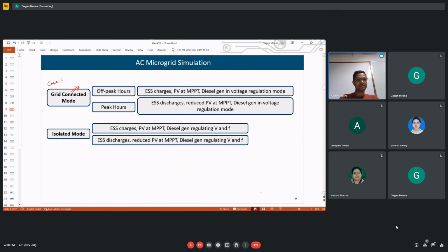So it is automatic, not manual. We don't have to give any instruction. As soon as the SOC goes below 30%, load will be curtailed automatically, because we have relays here. As soon as the controller knows that the SOC is below 30%, relay 3 will be opened. So load 3 will be curtailed.